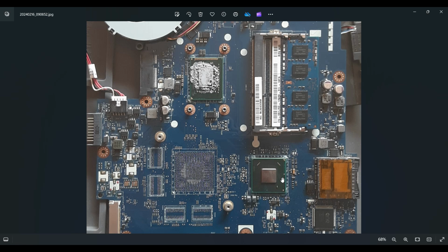Without data and clock, the motherboard will be in a coma stage. Even if you have voltages, there will be no use. Any voltage you consider, even processor voltages, PCH voltages, RAM voltages, all voltages, even if you are getting them, there will be no use without data and clock.